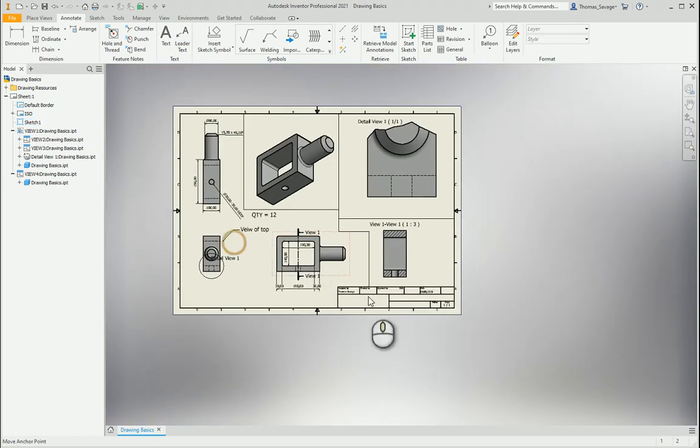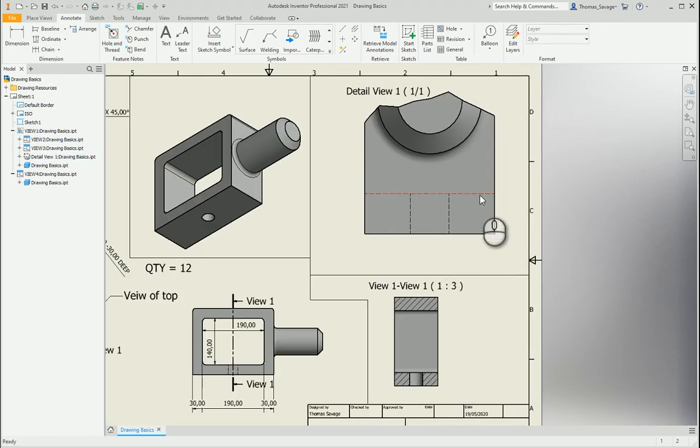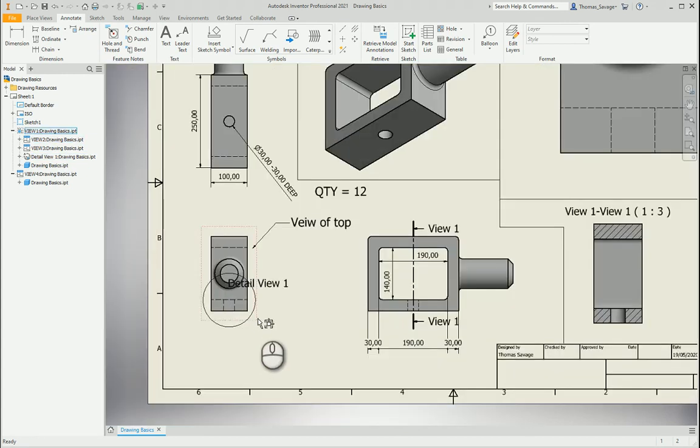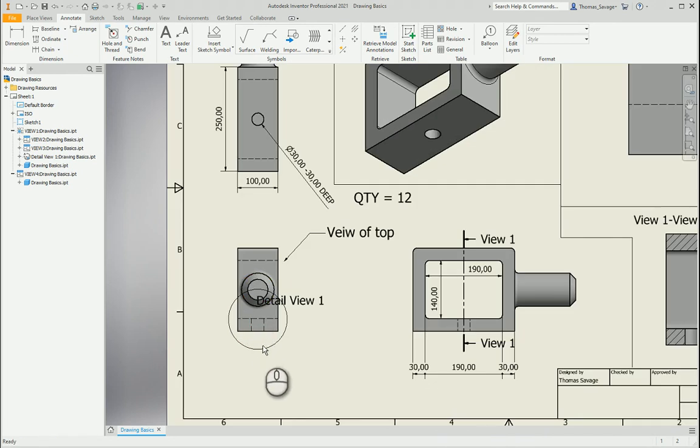What I am also going to show, I've just thought, is on this detailed view we have these dotted lines, which hopefully you understand drawings, and hopefully you understand that because we can't see the cuts that are in this detailed view, these lines just show where the cuts are. So if we dimensioned here to here, it'd be 30 mil. Because it says it's here, it's 30 mil.